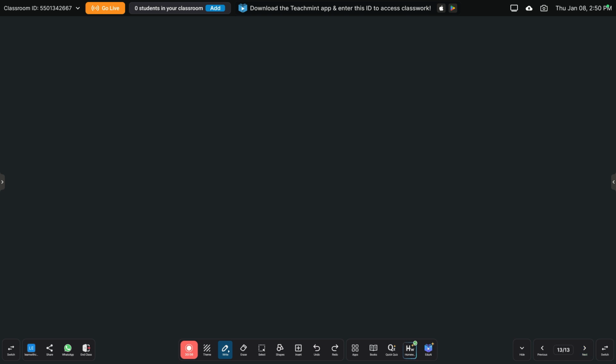Right. Now the instantaneous power, how do you define it? The instantaneous power is nothing but the product of the instantaneous voltage and the instantaneous current. That is Vm sin omega t multiplied by Im sin omega t. So what will you get? Vm Im sin square omega t.